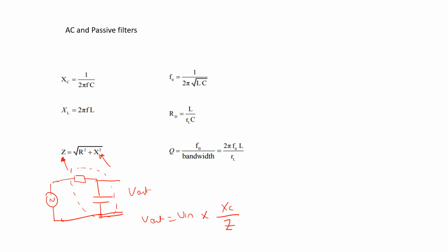What else can I say about this? Capacitances are usually small. So if you've got something that says something like 100 nanofarad, and you're working it out, make sure you put 100 times 10 to the minus 9. Okay. Other than that, I think those equations speak for themselves, but they're easy equations to use.